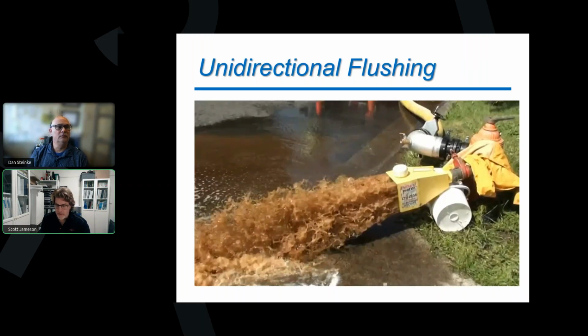If you've got higher pressure zones in your system, you're going to get more flow when you open up that fire hydrant, and those values are going to be higher for you. And if you've got a really low pressure zone, you might not get to those minimum velocities that we want. So it definitely has an effect.